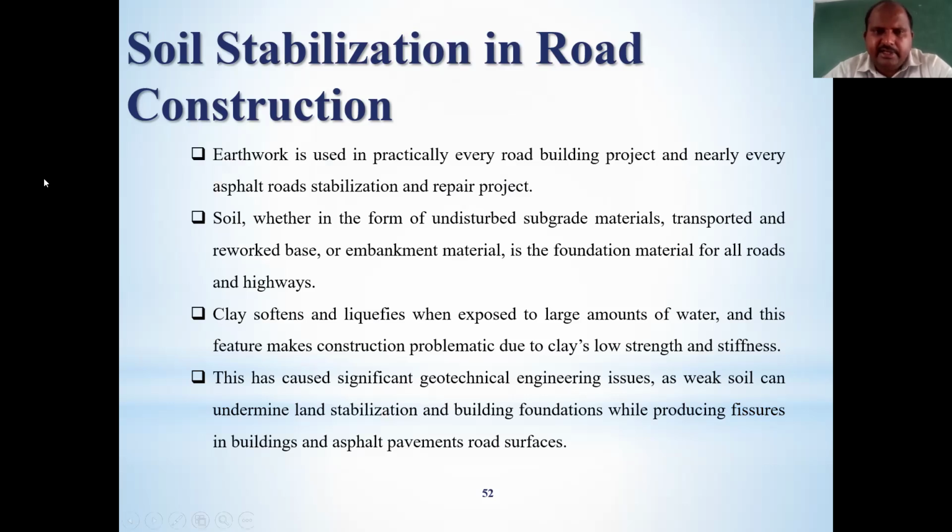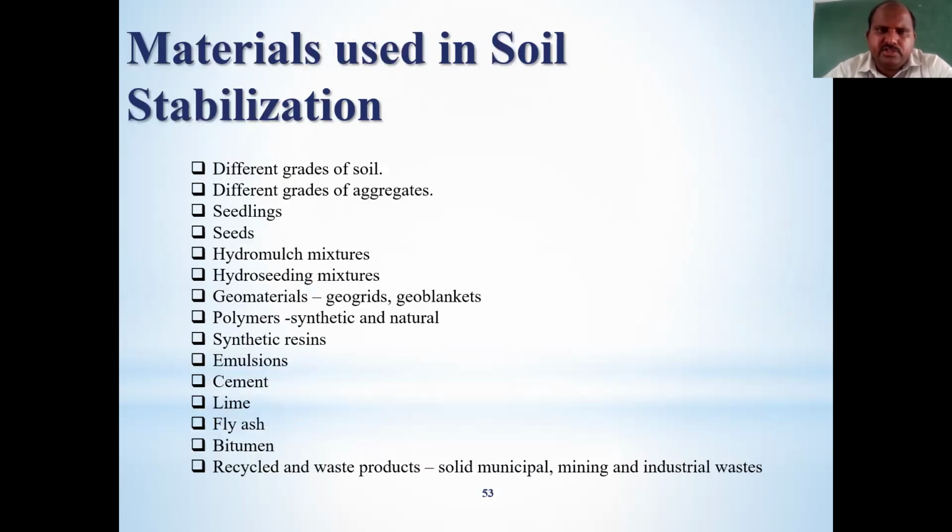Clay softens and liquefies when exposed to a large amount of water, and this feature makes construction problematic due to low strength and stiffness. Finally, this causes significant geotechnical engineering issues, as weak soil can undermine land stabilization and building foundations while producing fissures in buildings and also the asphalt pavement road surfaces.